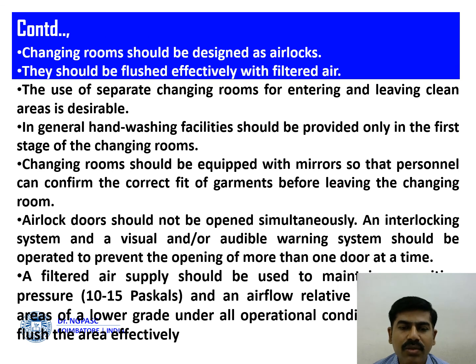So the changing rooms should be designed as airlocks. They should be flushed effectively with filtered air. The use of separate changing rooms for entering and leaving clean areas is desirable. In general, hand washing facilities should be provided only in the first stage of the changing rooms. The changing rooms should be equipped with mirrors so that personnel can confirm the correct fit of garments before leaving. Airlock doors should not be opened simultaneously, and interlocking systems should be followed.